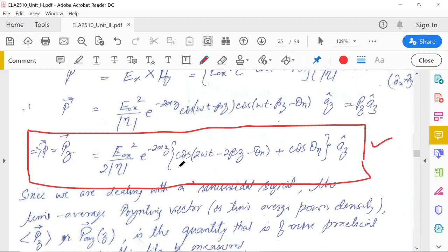So now we can say the power will be attenuating. It is moving in the Z direction. This power will also attenuate as you move in space by the factor e to the power minus 2 alpha z. These all remain constant. So the power will also decrease as it moves into space, because the magnitudes of E and H both decrease. Now the rate of decrease is twice that of E and H, because we have minus 2 alpha z. We can understand this easily because we have E into H. So the decrease will be faster for the power.